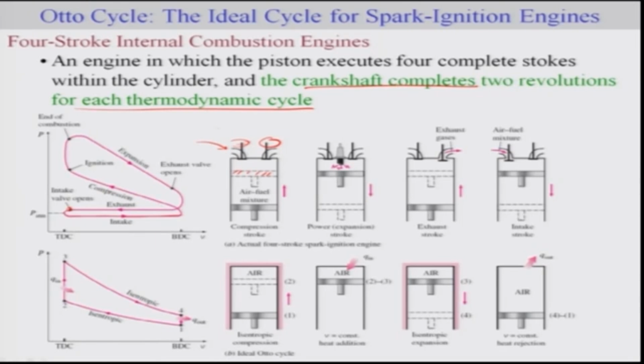And then the compression stroke takes you to the point where it's sufficiently compressed that you can start your ignition. So this is where the second state is. Ignition happens, this ignition initiates the combustion, which ends here, and after the combustion this expansion happens. The combustion ends here and this expansion is shown by this stroke, so this becomes the second part of the stroke. Then the exhaust valve is open.